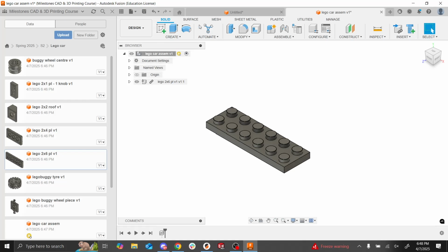So when you first create a part or a drawing, we have this origin here. But when you drag in a component into an assembly, it technically has no reference to everything in space. So the first one is grounded just so it doesn't move.